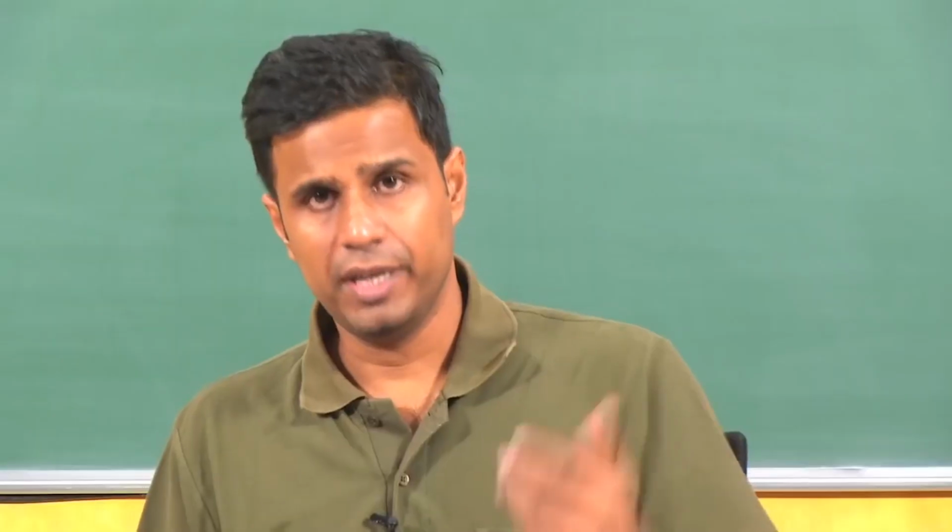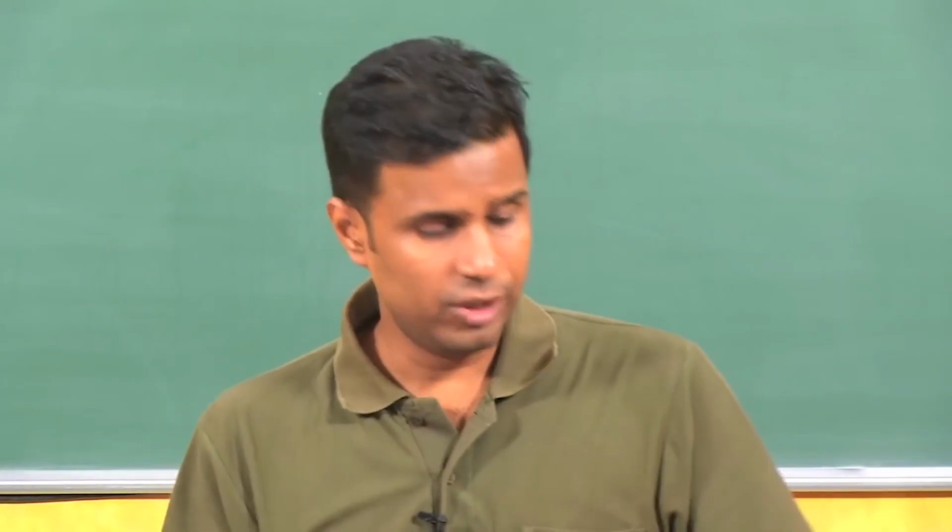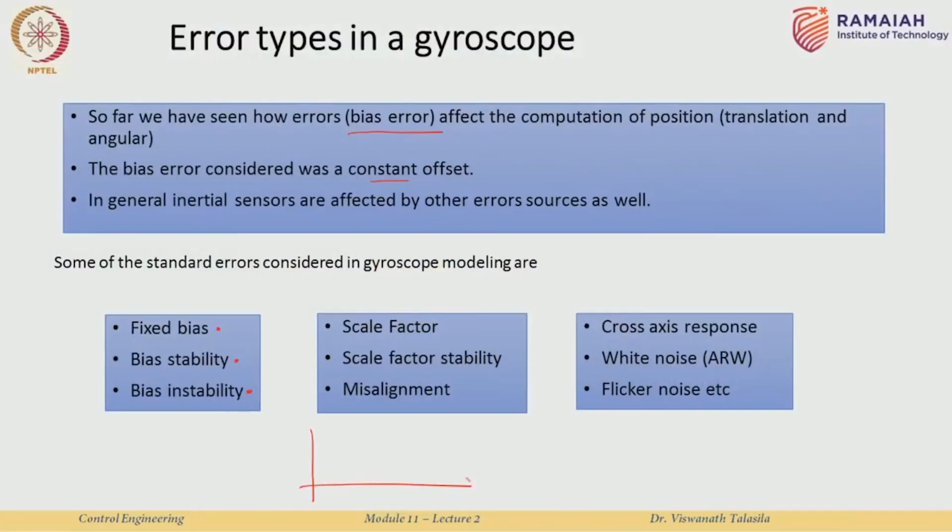You turn on your gyroscope, a MEMS gyroscope, and you keep it in a perfectly stationary condition, okay. So, let us say we are looking at one particular axis, it can be any axis, as a function of time in a perfectly stationary condition, okay. So, it may have some noise like that, right. This is the 0 value. It may have some slight deviation from 0 over a function of time, and when you take this entire data and compute the mean of it over say about 5 minutes, you will get a particular value. So, we will call it noise 1.